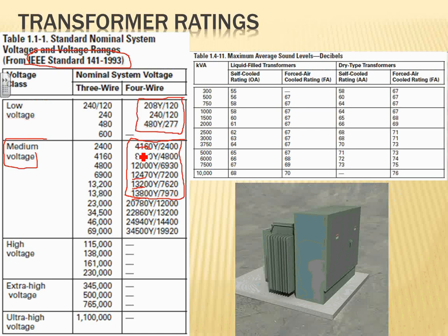At the high voltage level, that becomes your utility side. These are the transmission lines coming to Minneapolis, 115,000 volts coming on a transmission line to downtown Minneapolis to feed all these buildings. I personally dealt with up to 138. We designed a system for a data center. We brought in a feeder at 138,000 volts on the primary side and took it down to 13.8. Any comments, guys, about the voltages? Because you're going to encounter these voltages in the power system as well as for the transformers.